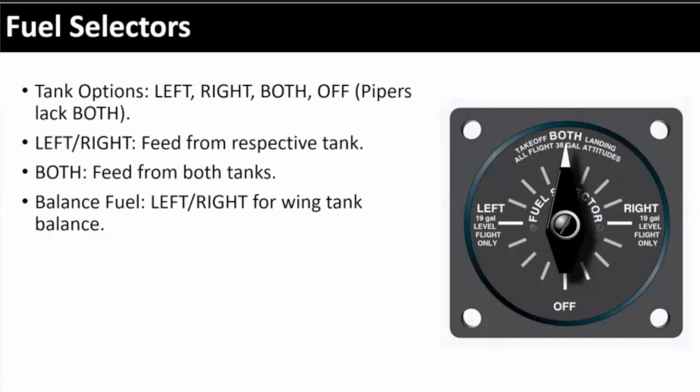All right, fuel selectors. Again, we've got fuel in 2 wing tanks, right? Okay. You have the ability to select which tank you want to pull the fuel from. Okay. You can have left, I want to use the left tank, I want to use the right tank, I want to use both, or, not optimal when you're flying, none. You don't want to set it for off or none, okay? But